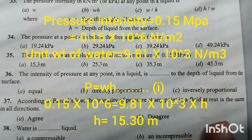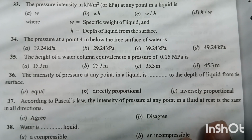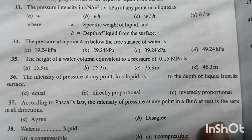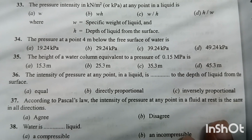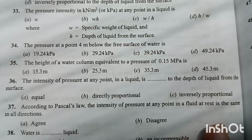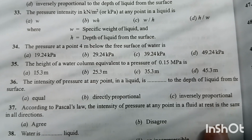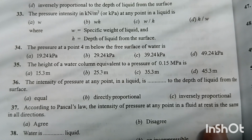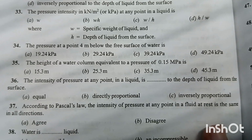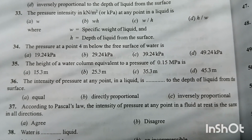We know the formula of pressure, intensity of pressure P equal to W into H. So intensity of pressure is given here 0.15 MPa, that means 0.15 into 10 to the power 6 Newton per meter square, and W is the specific weight of water, which is equal to 9.81 kilonewton per meter cube, or 9.81 into 10 to the power 3, into the height of water column. So if we calculate, the value will be equal to 15.3 meter. Option A is right answer.